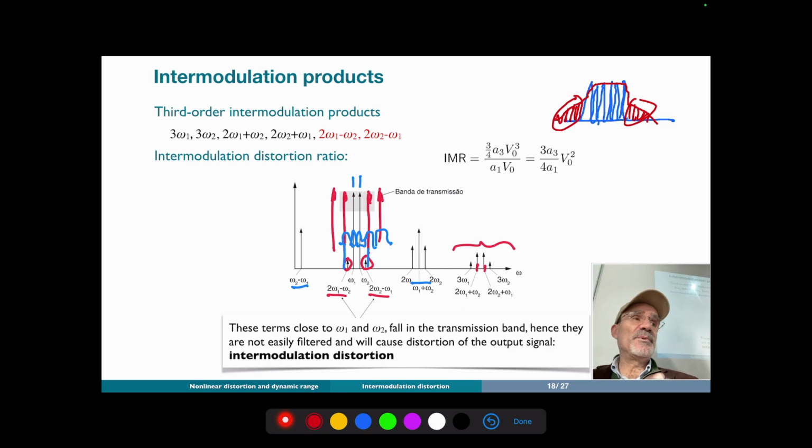And this is very important in wireless applications, especially in a transmitter. The last stage of amplification, to provide sufficient power for broadcasting the signal, has to be a power amplifier to provide sufficient gain. And this power amplifier is usually operated near the distortion region, which may produce these kinds of effects, which are undesirable and affect the performance of the system.